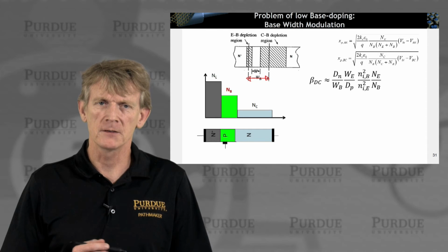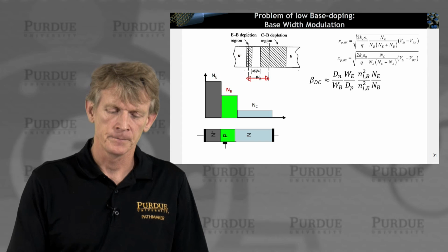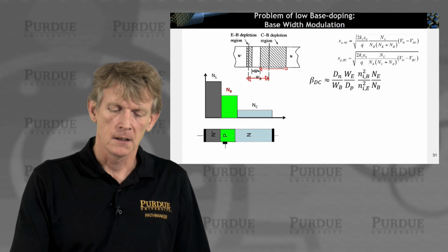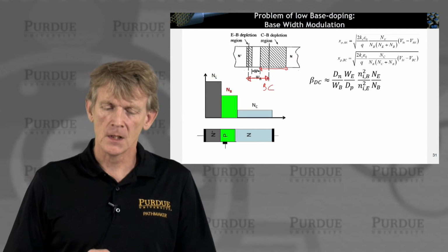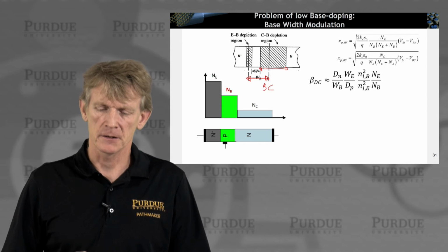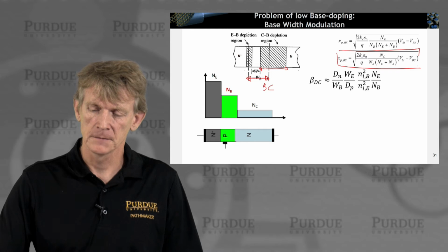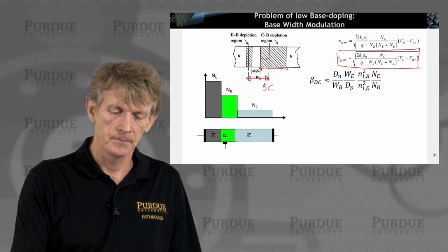But we know that we have a depletion region in those junctions on the left and the right. And the component on the right, the base collector junction here, is infringing or creeping into the metallurgical junction. And I can calculate that value. That's this XP.